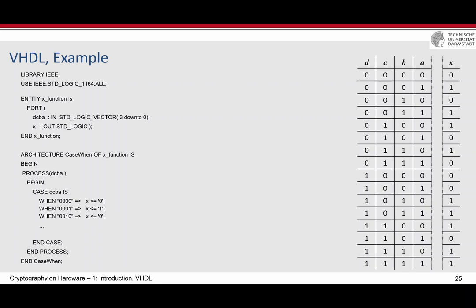It means that instead of doing this by hand, by Karnaugh diagram, this is the job of the synthesizer. And synthesizers usually do a good job when the number of inputs of the function is small, for example, 4-bit or 5-bit. If it gets to 8-bit, then it will be much, much larger, and the synthesizer will usually not do a good job. It is fundamentally hard to optimize a circuit with more than, for example, 6 inputs. And then if the function has a larger number of inputs, most of the time it makes sense to manually optimize it yourself.